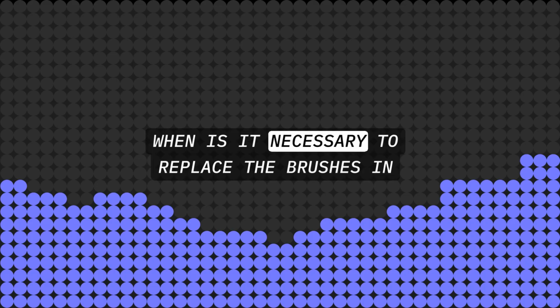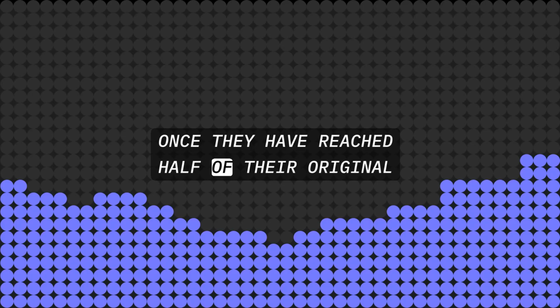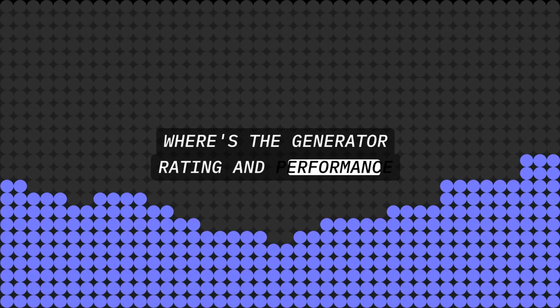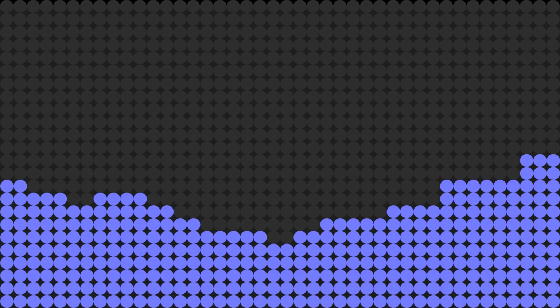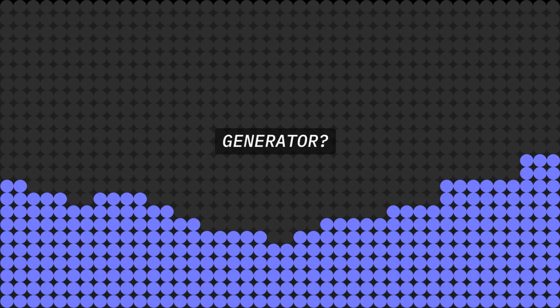When is it necessary to replace the brushes in the starter? Once they have reached half of their original length. Where is the generator rating and performance data located? On the data plate attached to the generator.